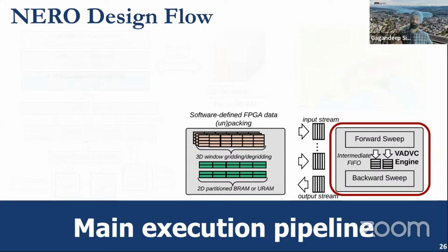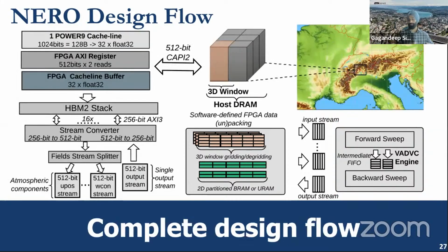Once we are done with the processing of this data, we send the data back to the HBM channel, or we also provide a switch if you don't want to store the data in the HBM memory, or if you want to offload directly to the host CPU system, you can do that. So we have quite a bit of flexibility in our design in how the data should be mapped. And the complete design works in a dataflow manner, so everything is in a pipeline fashion, and you get a large amount of task-level parallelism.